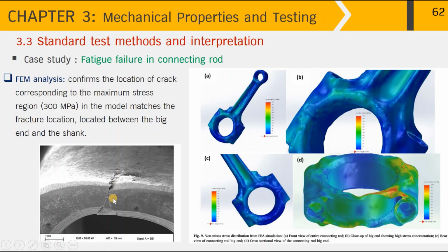So this is how we investigate fatigue failures in engineering components. Although it's unfortunate that this fatigue failure happened, it is necessary to investigate to see the root cause of the fatigue failure so that we can fix it by looking at where it started. And once we find out the cause, we can either change the design or be careful about the metal processing of the component, with a refined microstructure and without inclusions or defects that can be the weakest link for fatigue crack initiation.